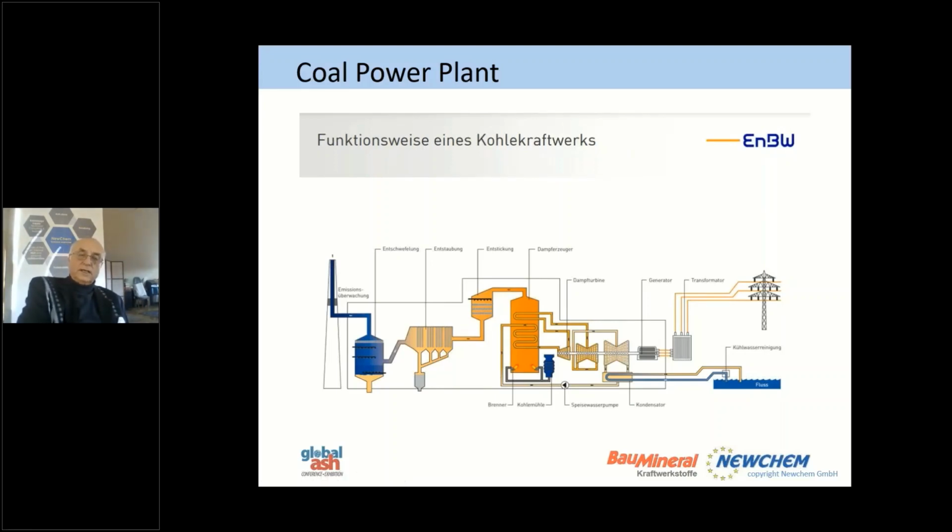So these filters are actually electrostatic filters, and on these filters there is a certain vacuum. So when the gases pass by, the small particles of the fly ash are filtered on the top of the filter, and from time to time the vacuum is reversed, so they will fall down here into this cyclone to be separated. And as this is happening in the warm atmospheres, we are very happy not to have to dry